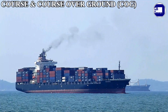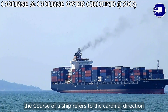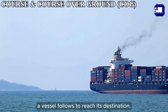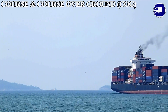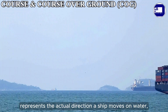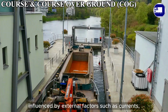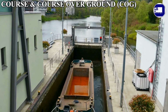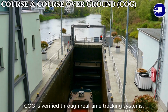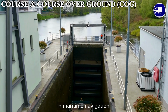Course and course over ground (COG). In navigation, the course of a ship refers to the cardinal direction in which it is steered, essentially the planned route a vessel follows to reach its destination. However, the course over ground (COG) represents the actual direction a ship moves on water, influenced by external factors such as currents, winds, and tides. A ship's course is measured in degrees, while COG is verified through real-time tracking systems. Both are essential for ensuring precision in maritime navigation.